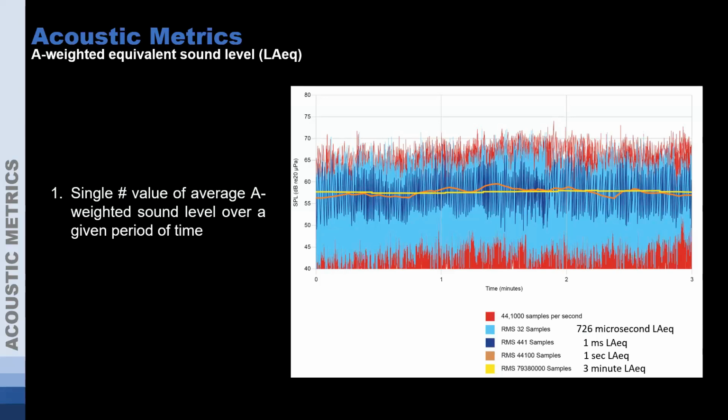These types of things, they're not always using an LAEQ, but that A in there is the same here, and that weighting, similar to what we talked about in the NC curve, is weighting out that low frequency sum, so it's going to be more what the human ear typically hears.